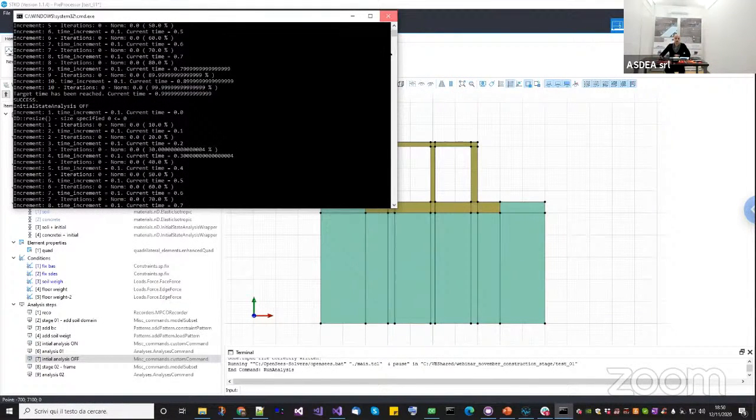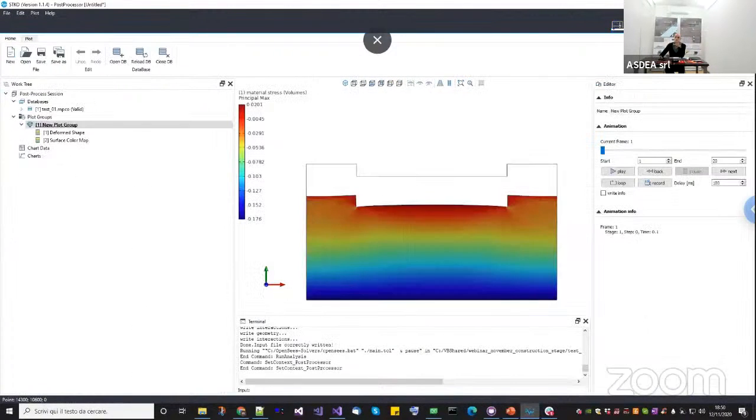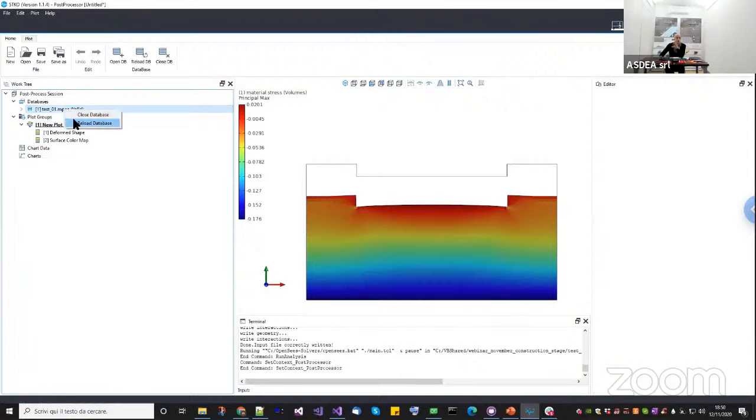Now the nice thing about this is that my soil domain will still have the same exact stress field, because the strain field of the initial displacement analysis has been stored into the material. But the displacement is now reset to 0, so that when I put in my new structure, it will not bend, because it doesn't see any initial displacement. And so this one will give me the exact solution, at least for this moment. Then I will show you that we are going to have some problems later on.